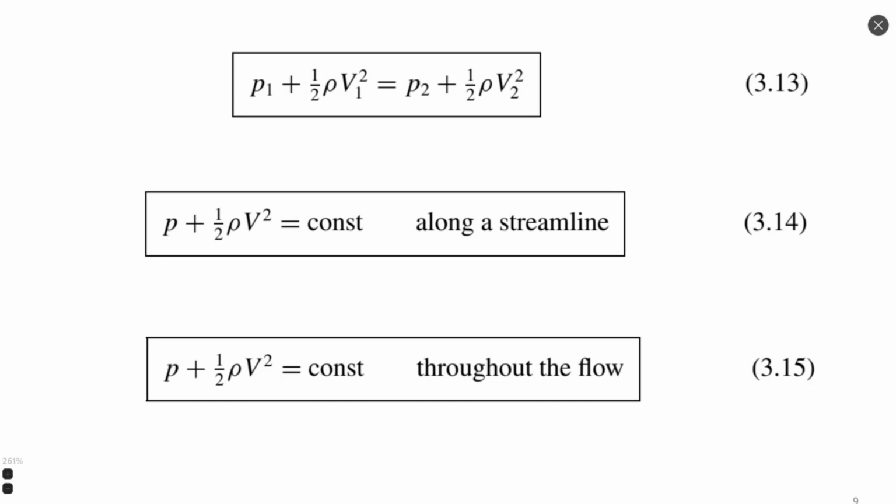Usually we apply such an equation to a big volume where we can determine two sections of interest, for example entrance and exit, and in between the transformation of flow quantities. And because flow is incompressible, such a Bernoulli equation is very simple and can be solved in many different applications.